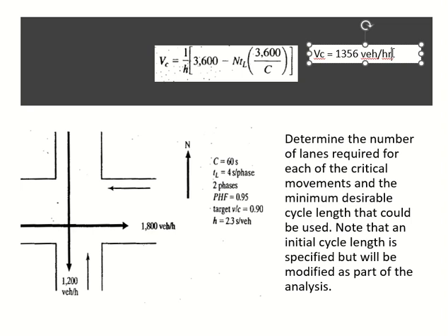They will be divided. So I'm no longer worried about 1,800, because they are now passing in pairs. So how many from one lane? 900 from each lane. So I have to worry about 900, because the other 900 will pass simultaneously.